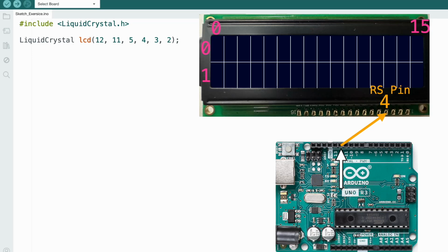This is us actually putting a wire in there, right? We have to do that. The LCD library is expecting that whatever the signal on 12 is going to go to pin 4 on our LCD. And RS, we'll talk more about what the signals mean for this, but it's just called the RS pin. That's the 4 pin, right? 1, 2, 3, 4, not 0, 1, 2, 3, but actual 1, 2, 3, 4. 12 will go to the 4 pin on our LCD.